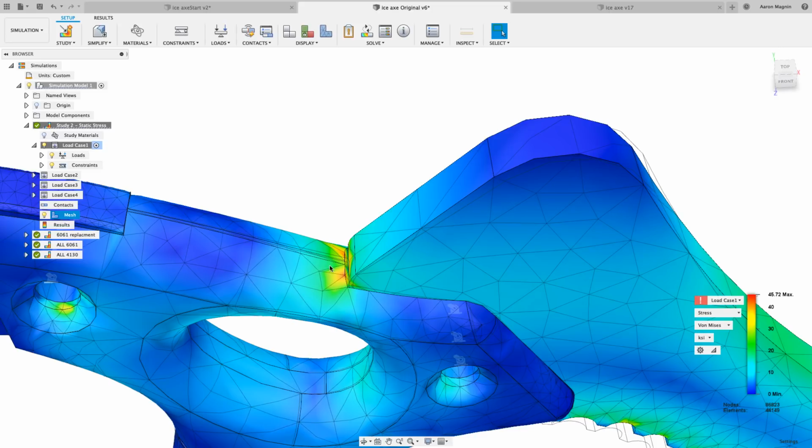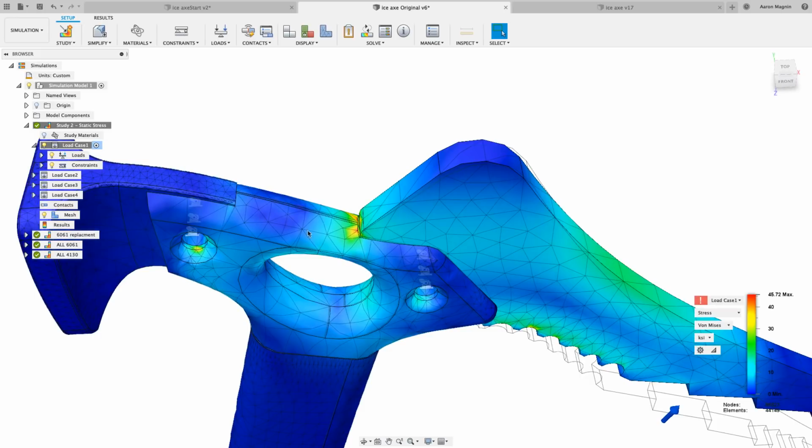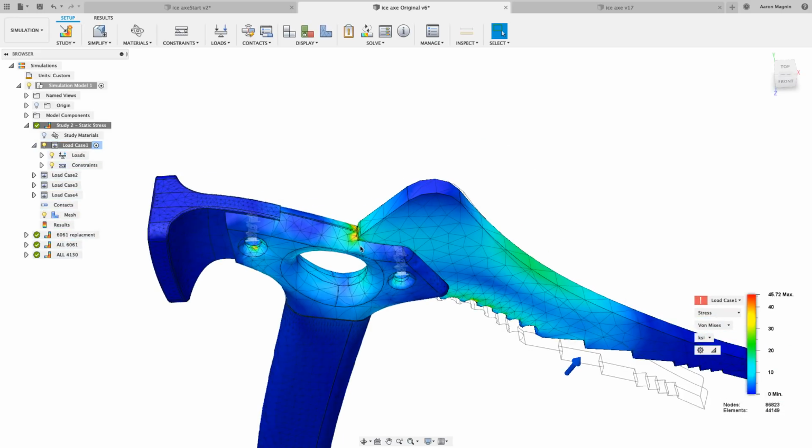And obviously this mesh, and I just showed it here by clicking the little hide show right there, this mesh isn't all that fine, so I'd actually want to refine it to really understand if there is a singularity happening there. But it's something to consider, something to think about, and something that we can take with a grain of salt when we're looking at some of these results.